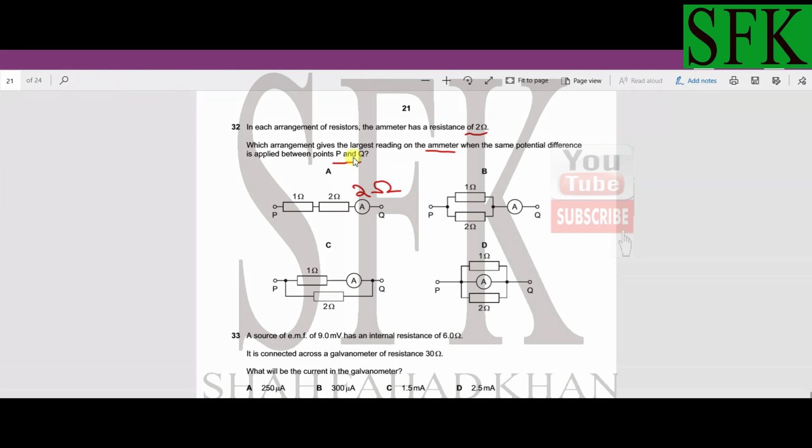Now, one thing to remember over here is that the lower the resistance, the higher the current. This is the rule because we know from Ohm's law that V equals IR. If voltage is constant, as they told us in the question that the same potential difference is applied, then current and resistance are inversely related. Now let's see the circuit that has the least resistance.